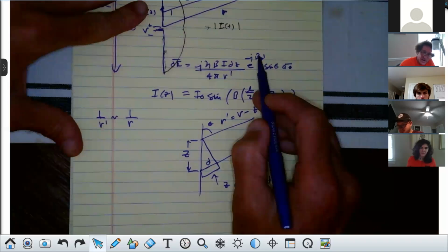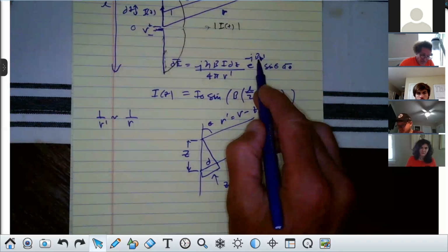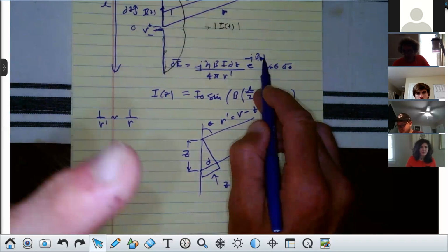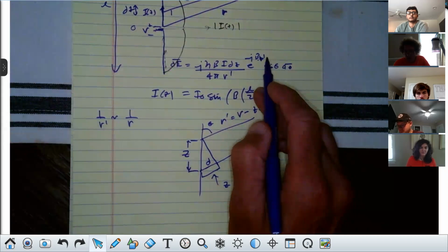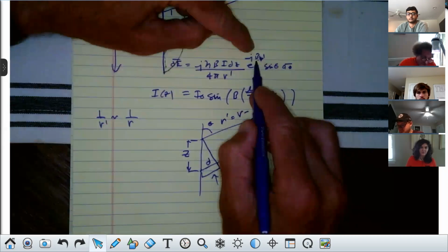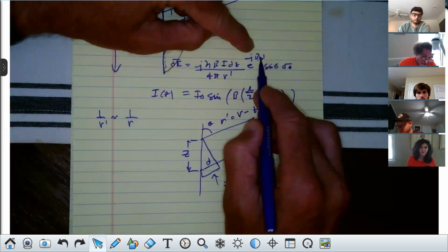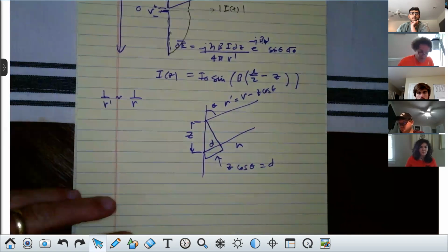This term, beta? Beta is 2 pi over lambda. I mean, this argument here, minus j beta r, it could go from 0 to 2 pi, from 2 pi to 4 pi, from 4 pi to 6 pi. Every time you add 2 pi to it, really we're winding the clock, aren't we? But when we have beta times this, just listen to me on this and you'll understand. That R value now, a small difference will mean a large difference in beta R, and angularly. You'll see this here in a second, if you bear with me.